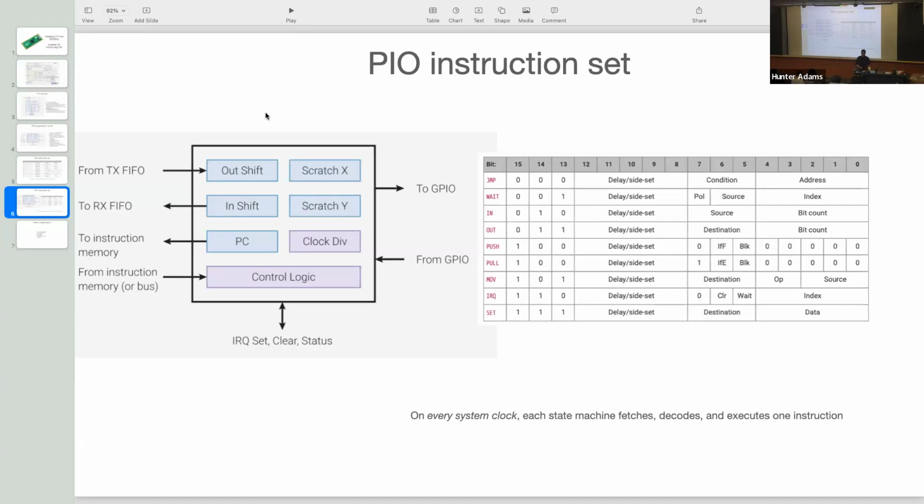Yeah? So there's only a 3-bit opcode, you have 9 instructions, because push and pull are in the same opcode, but then use bit 7 as like a 4th opcode bit? Yes. Yes, precisely.